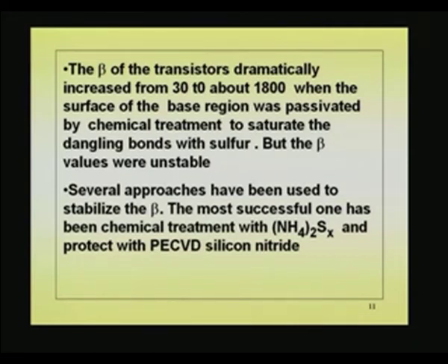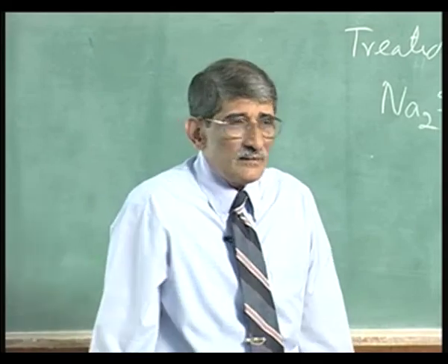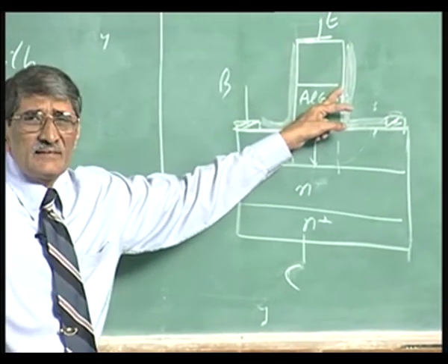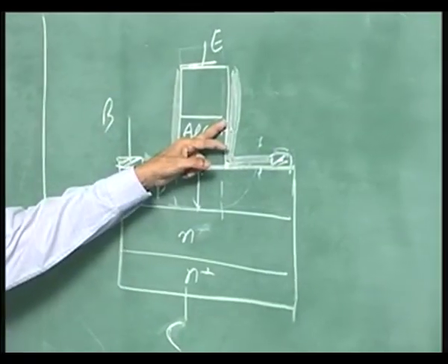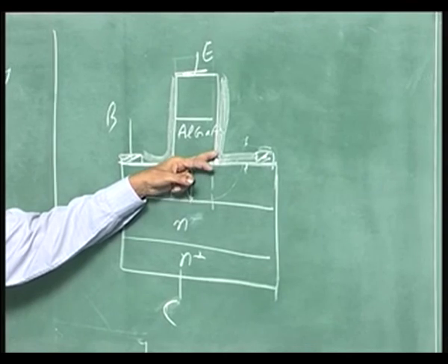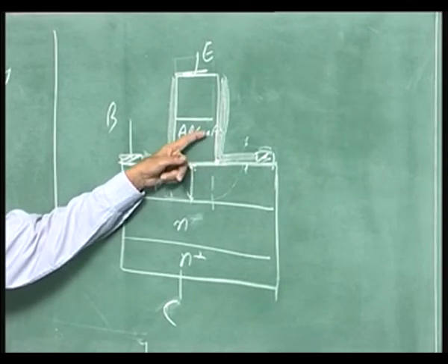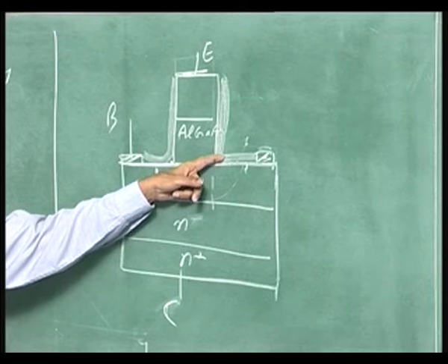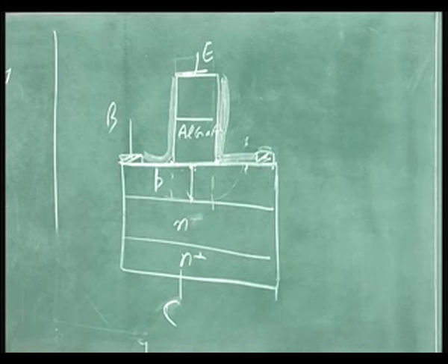Number two, the sodium sulfide layer on the surface gives rise to some leakage current across the junction here. You do not like any sodium or potassium contamination. The sodium sulfide gives rise to leakage there. So, barring that leakage, the beta went up. To remove that sodium, it was dipped in water, and the whole thing went off.